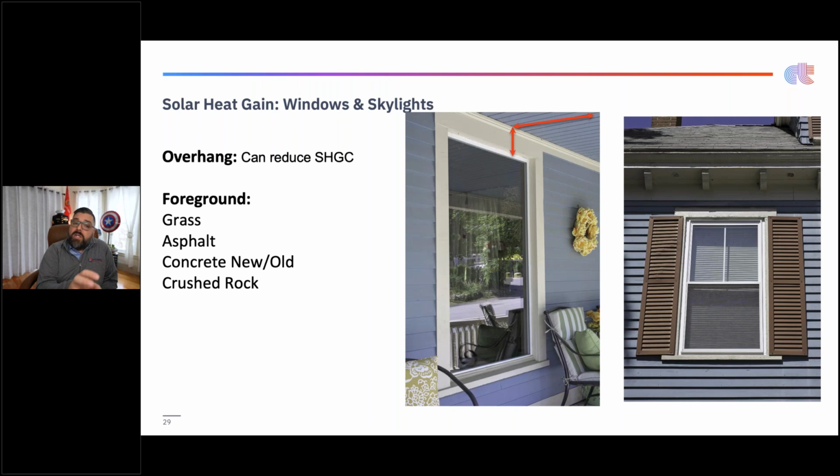So as an example, this is a picture on the left of my house. I have a nice farmer's porch. I love it. I get yelled at for not using the furniture out there enough during the summer. But you can see we don't have shading on this window internally because I have an 8-foot porch that sticks off the front. It's about a foot up, but 8 feet out, and it provides awesome shading for those windows. If I didn't include that, the gain on this window alone would drive the heat gain up drastically for that room and the total. We have to make sure we account for not just internal shading, but exterior shading when it makes sense as well.